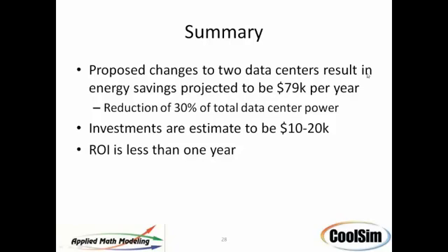Yeah, it's hard to generalize, but what you'd have to do is just run a couple of models with different fan speeds, and see what the lowest one is that you can tolerate, and then recompute some of those energy parameters. It can be quite significant, Jen, because the relationship between the power to drive a fan and the flow rate coming out of it is a cubic relationship. In other words, the ratio of the RPMs before and after, cubed, ends up being the difference in power. So it can be quite significant to let those fans come down.